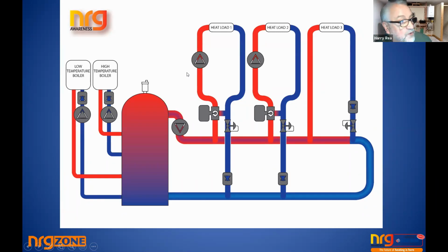And then as each zone decides to turn on a pump, it can take its correct amount of mixing. So again, a very logical way to do it. But to my mind, the buffer is a huge amount of water to heat if there's no reason. And secondly, it's going to take up a lot of room, and buffers are not cheap in any case.